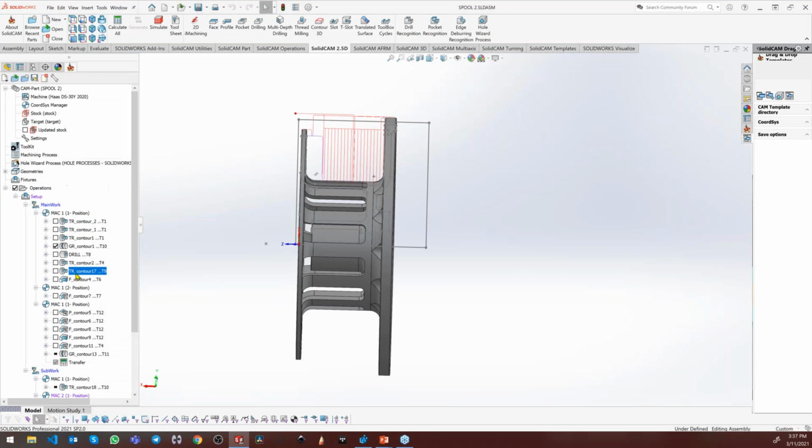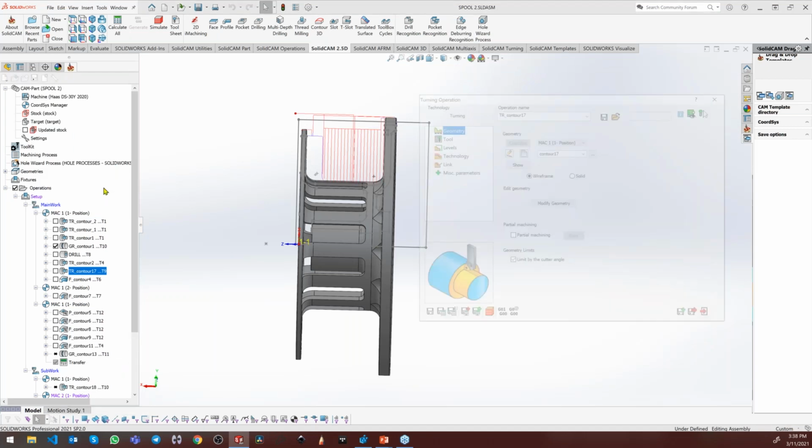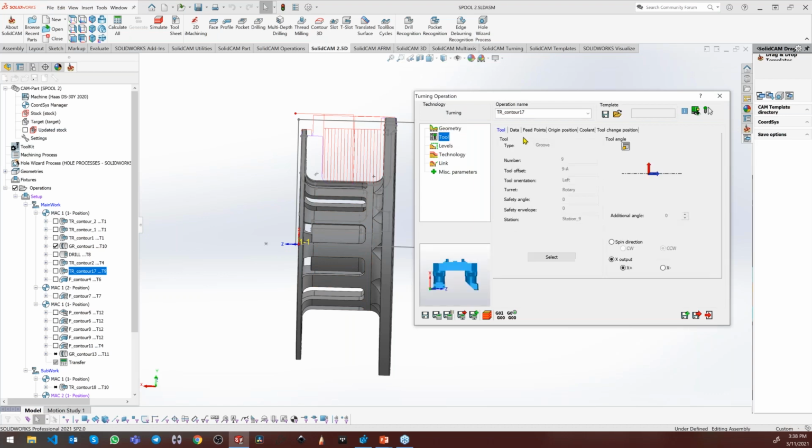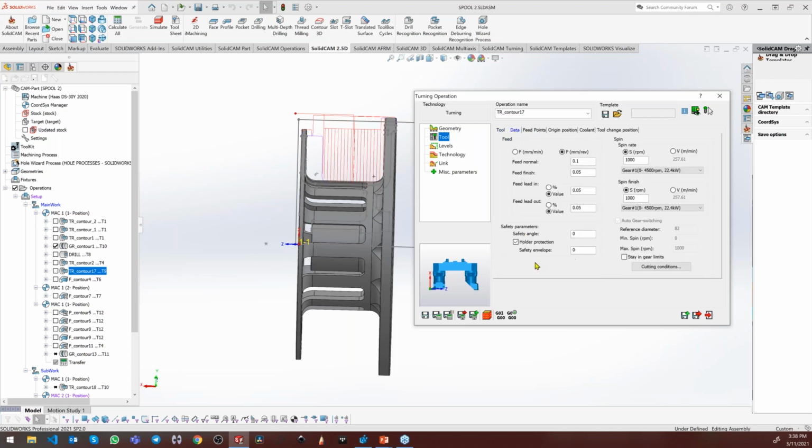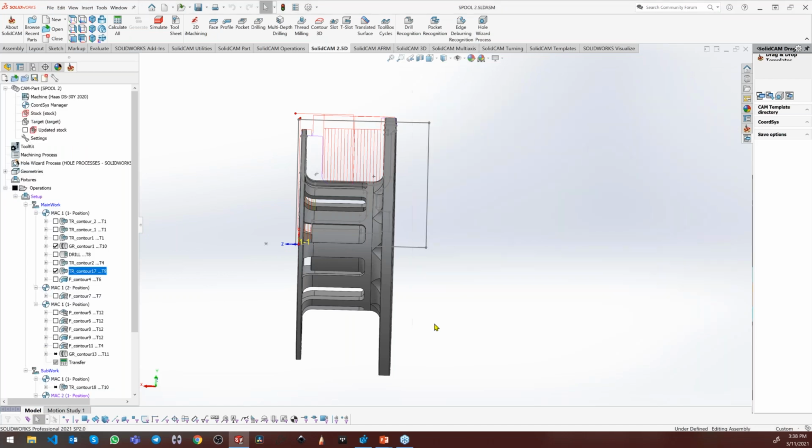So it's called a false collision, and to avoid it, today we have in the tool this holder protection feature. If you don't want to get this collision, you can just unselect the holder protection and you will get the tool path that skips the collision with holders. For face groove, internal turning tools sometimes, and also for some special tools, you cannot use 2D collision protection, so you can cancel it if you don't have a good tool path that you want to get. So it's also an additional feature for turning.